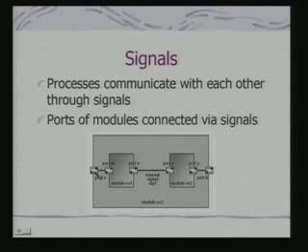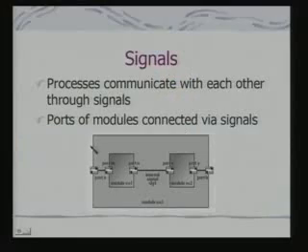And if we consider these part of a bigger module, module EX3, which consists of module EX1 and EX2, then these are the ports for communicating with the external world. So you can see how you are describing a hardware using an object oriented language. Along with it, you can even describe the software as well. This is the basic advantage of your SystemC, right.